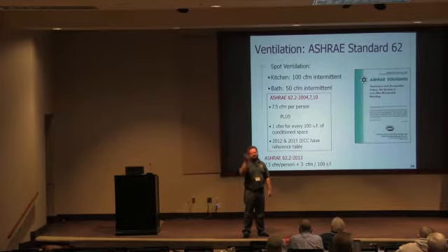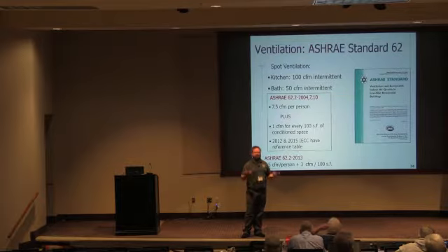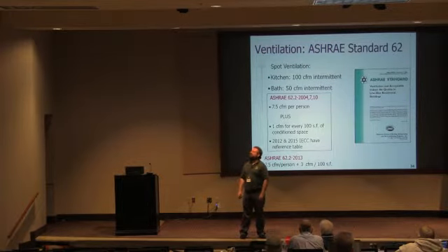So when someone puts in a 50 CFM bath fan and then they put it into a little 4-inch duct and they run it through 17 loops before it dumps into the attic. By the way, where should exhaust air always go? Outside of the freaking house. Yeah, come on, guys. You see them terminating into the attic, and then we actually get comfort calls where people have exhausts that dump into their attic, and then they call us and they're like, we got really high humidity. It's like, yeah, it's because your shower exhaust dumps into your attic. You should probably go outside.